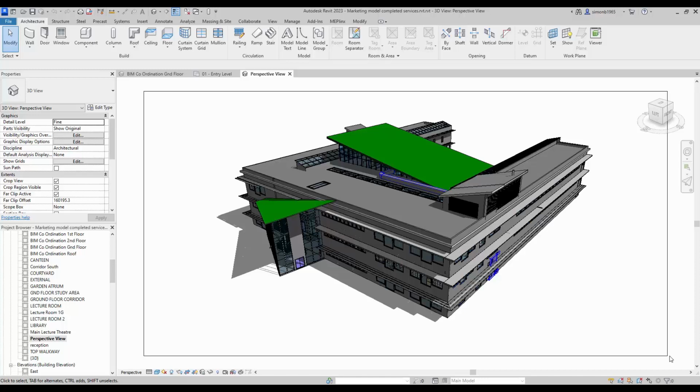This video shows the process involved in modelling a complex geometry building and surrounding buildings so you can correctly emulate the shading calculations on your target building. So the model we're using here is a typical Revit project. Effectively, you can see lots of different levels and different geometry.